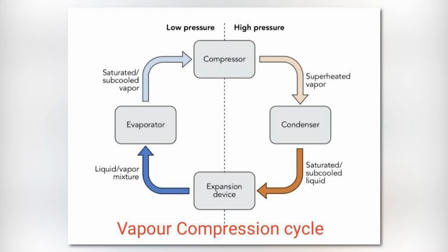No matter what refrigeration system is used, the refrigeration cycle follows these 4 steps: compression, condensation, expansion, and evaporation. The first step, compression, is performed by the compressor and consumes the most energy. Next, condensation occurs in the condenser, where heat is rejected to the environment as the refrigerant condenses. Next, the refrigerant is throttled through an expansion valve to reduce pressure. Finally, the refrigerant absorbs heat from the cooled area as it evaporates in the evaporator.